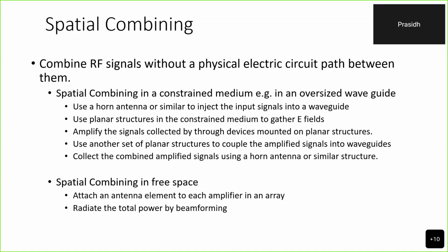When it was initially introduced, it basically consisted of something like an oversized waveguide, into which multiple parallel amplification stages were inserted, and then the structure was fed using a horn antenna, and the amplified signals were again collected using a horn antenna. So that was how the thing was conceptualized, say about 2 decades ago. Now there are different commercial products which we will be looking at in the upcoming slides.